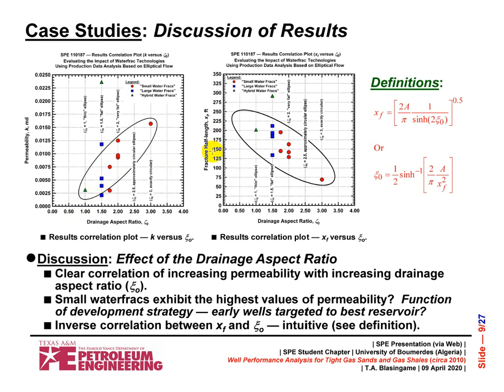Next is fracture half length, and in this case we're again looking at probably a little bit of bias because all the calculations are between 100 and 200 feet. We can see, though, there is some sort of a grouping of trends, and these smaller jobs did have a larger aspect ratio, which could be something to consider in your completion design. It could also be because they were in the higher permeability region.